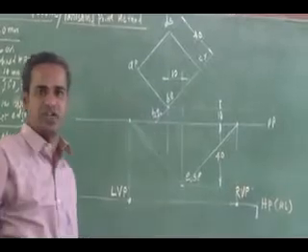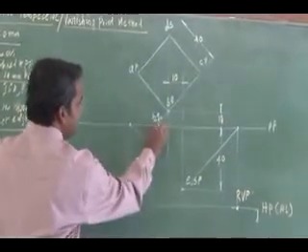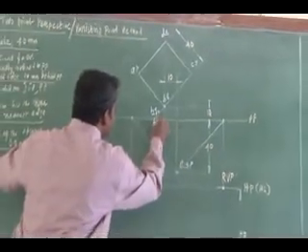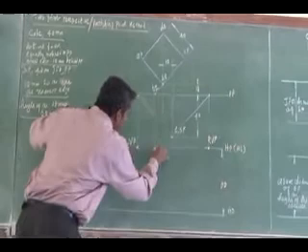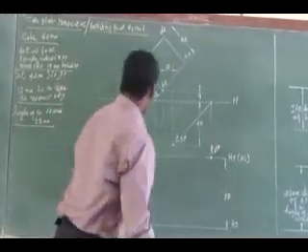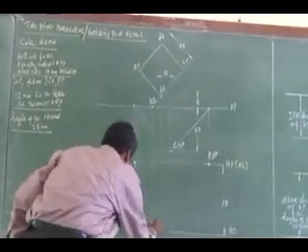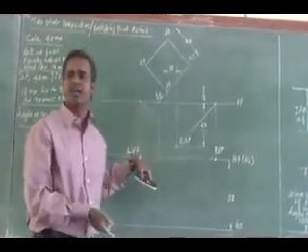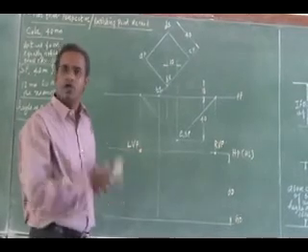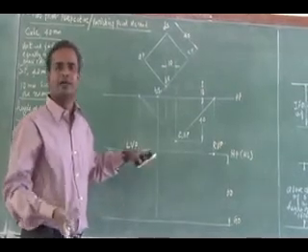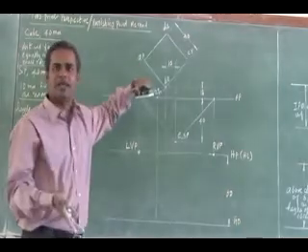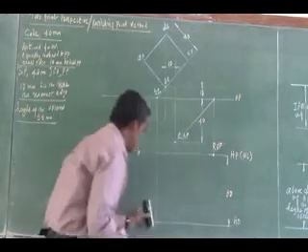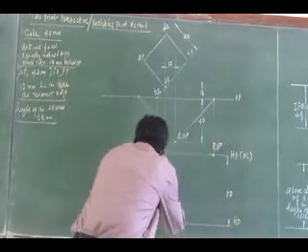Since none of the edges are touching, one vertical edge I am extending either parallel to the right vanishing or left vanishing. Now parallel to the right vanishing I have extended, I have marked B2 at an arbitrary location. Then I am projecting that to the ground plane. Now conveniently, the B2Q2 perspective I can draw to which height? 40 mm. That is the true height. Right, the cube's height is 40 mm, the side is 40 mm. So B2Q2 perspective I can obtain for exactly 40 mm.